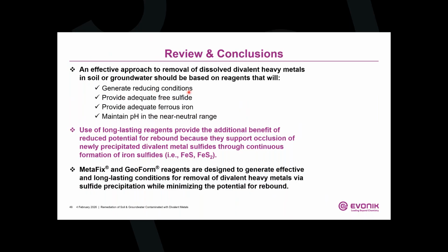We achieve this by creating reducing conditions, ensuring an adequate supply of free sulfide, an adequate supply of free ferrous ion, maintaining pH in the optimal range, and I would add using reagents that provide the sulfate reducers with the simple organic carbon and phosphate that's essential to their activity. Use of these long-lasting reagents gives you that occlusion, that lockup that is so important, and our Metafix and Geoform reagents have proven very reliable in creating those kind of conditions to take out divalent heavy metals and achieve remedial objectives.